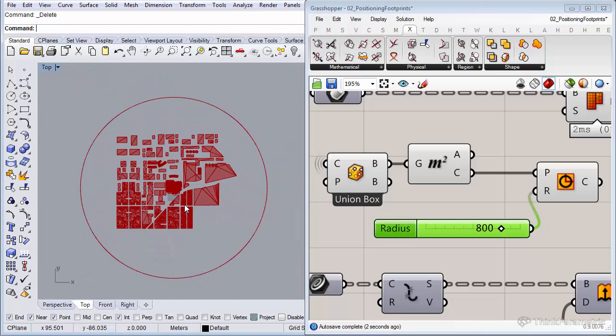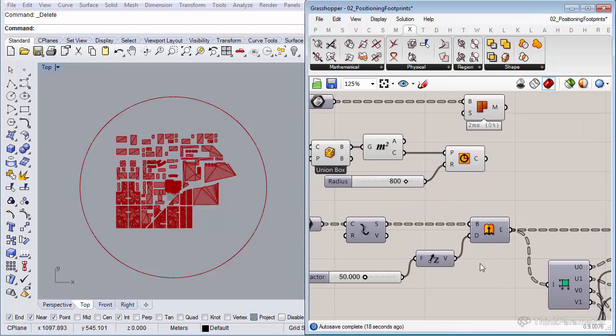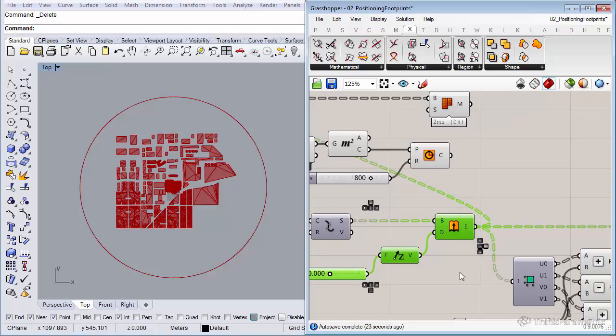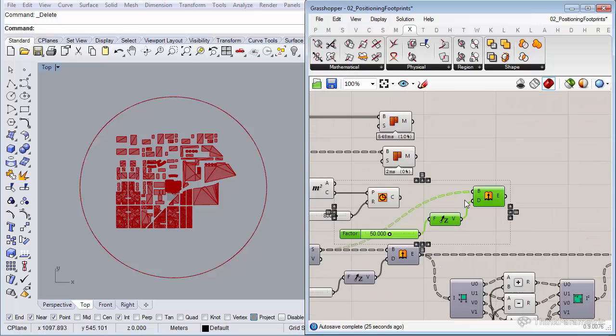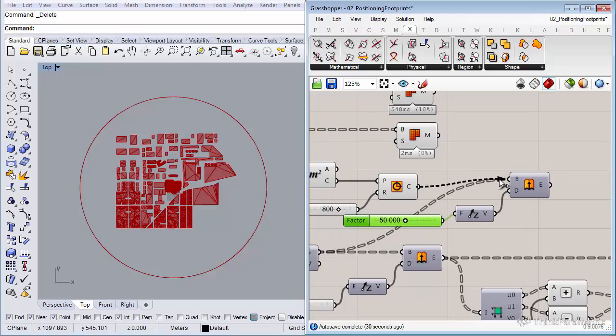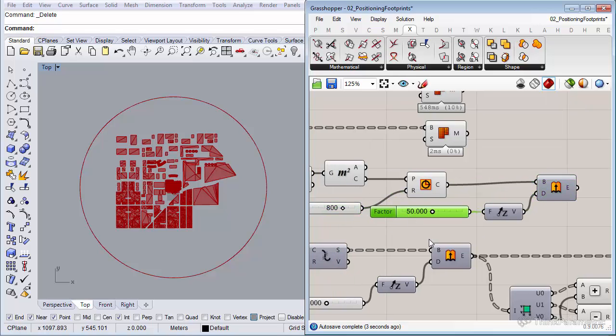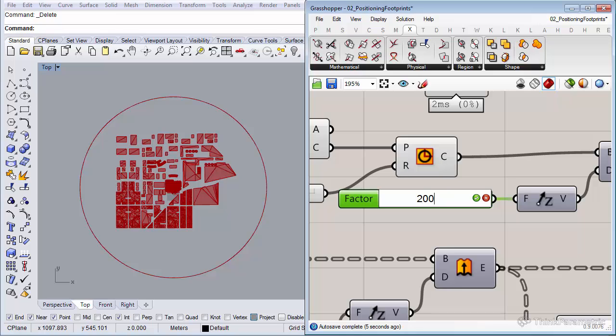As you can see in the top view in Rhino, we have a really big circle. If a view ray doesn't hit a surrounding building, at least it's going to hit the circle. And also let's extrude this circle like we did with the 4 plot outlines using the extrude B-rep component. And let's set this number to 200, like a big number. So it's like a big wall.